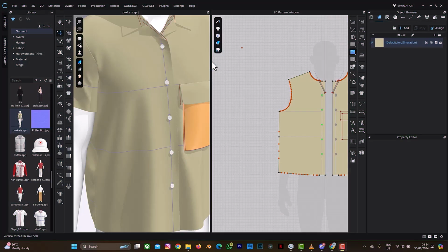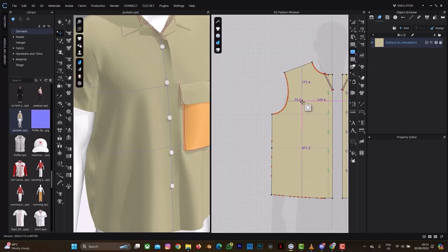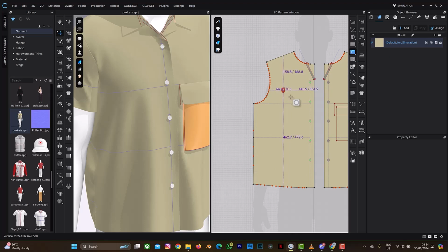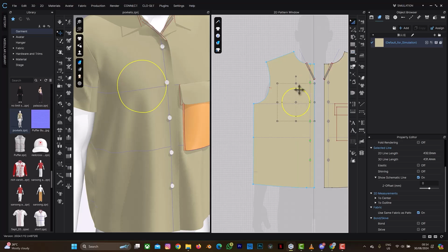Okay, let's create our shaped pocket. So we'll be using this. So I'm going to select this, hold on it with your left click, and select internal ellipse. So I'm going to create an internal line here. So just drag it depending on the size you want. Okay, I think this is okay. So I'm selecting A to move it to a proper position.